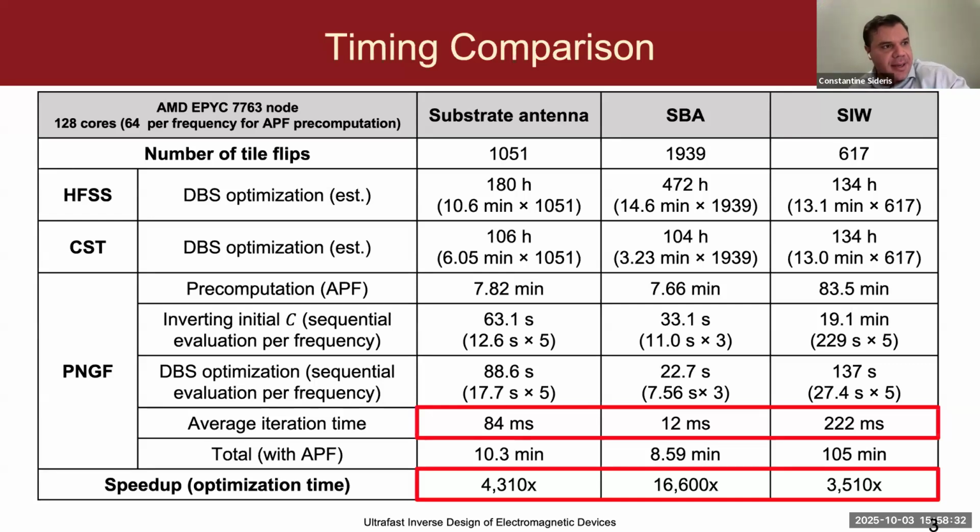Yes, these are all great questions. So in the examples where we use the finite difference frequency domain solver, it's really difficult to get very thin metals represented with finite differences, just because the complexity of the method increases and you have a Cartesian grid. So for those, we just assume that you have a single flat surface, and we tried to make the DZ such that it matched what the metal thickness would be.